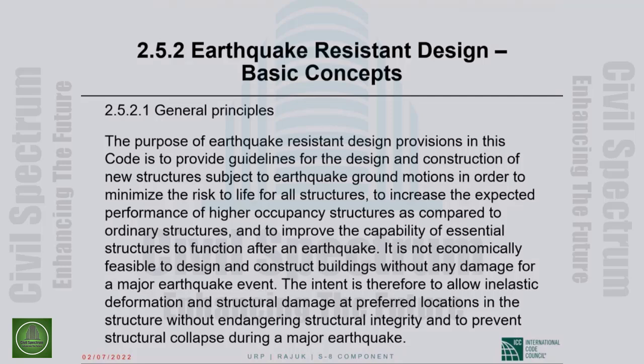That is very important. The structure should still be standing up, although it is damaged, and to prevent structural collapse during a major earthquake. Okay? So that gives you the principles which are very, very important. We are not designing for elastic response to the design earthquake.